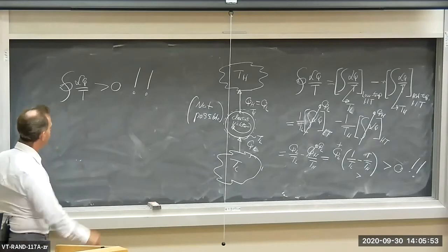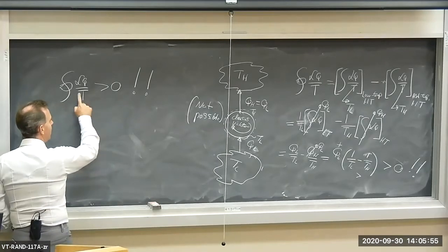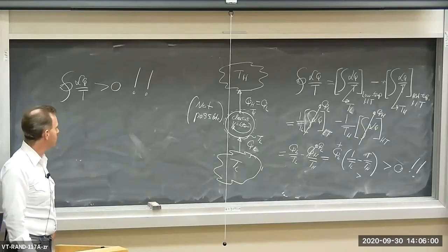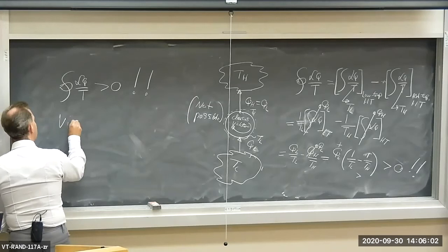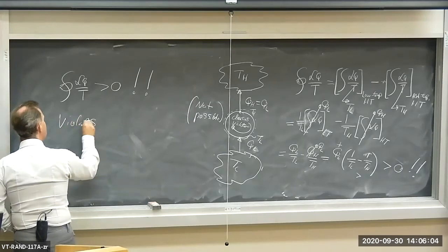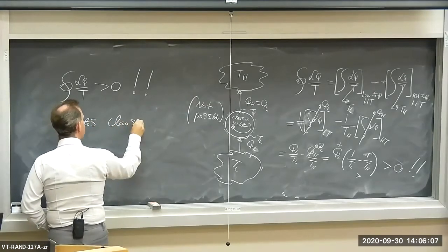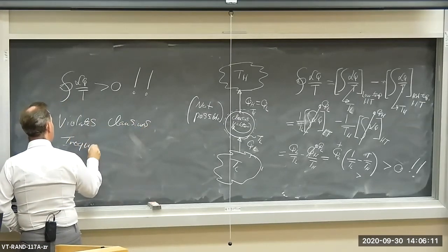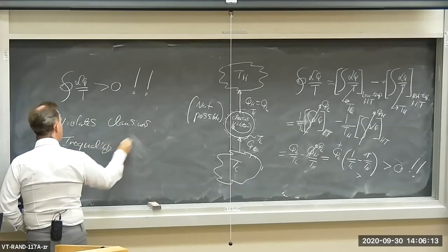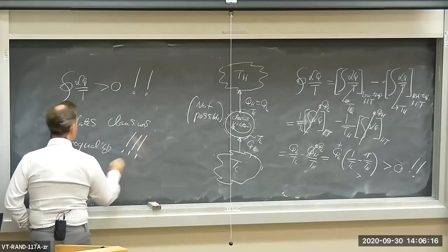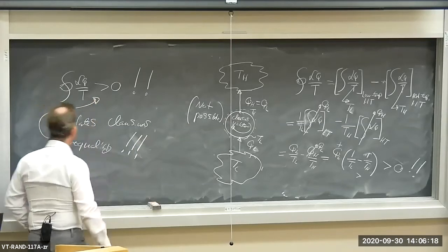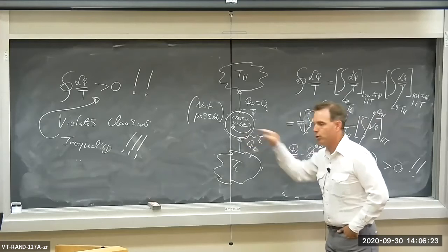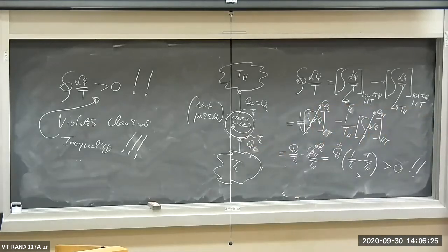Nope. The Clausius inequality says that this integral has to be less than or equal to 0 for any device. This violates the Clausius inequality. This device is not possible, according to the Clausius inequality.